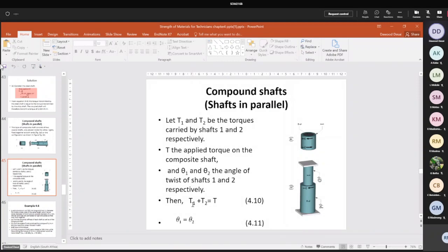The general formula in the front, you apply it to any section or any segment of your shaft, whether it's series or parallel, doesn't matter. The only thing that's going to change is the diameters. Of course, the J value is going to change. The length can change. If it's different materials, the G value will change. Very, very simple stuff. So I'm just teaching you the principle here. After that, it's simple mathematics.